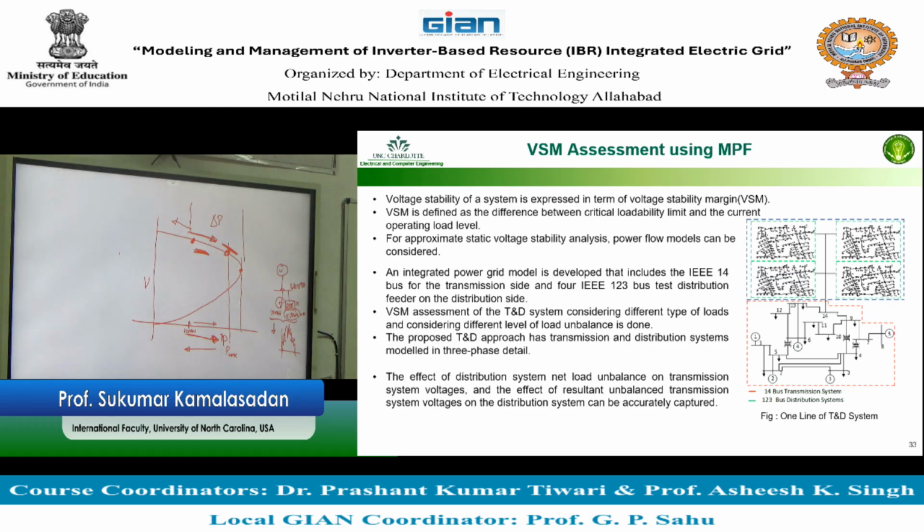So I'm now making a list here. One item on the list is maximum. The second item is margin. When PV comes, the first thing you can do is operate safe, and at what point you can operate safe. And then you can also say how much control. You need to control the PV with the reactive power from the inverter. Who is doing all this stuff?